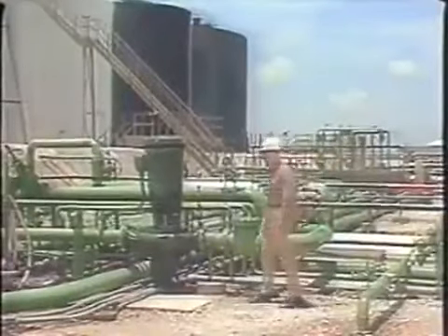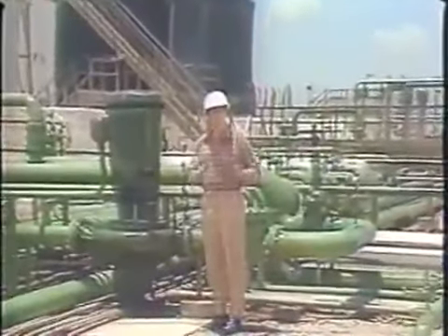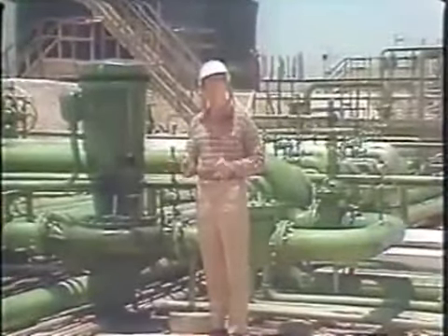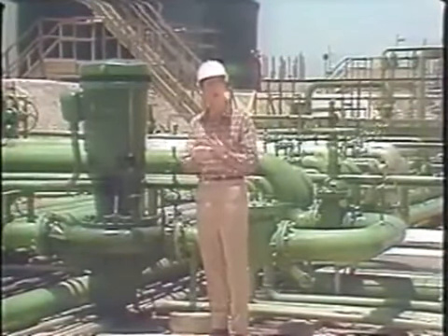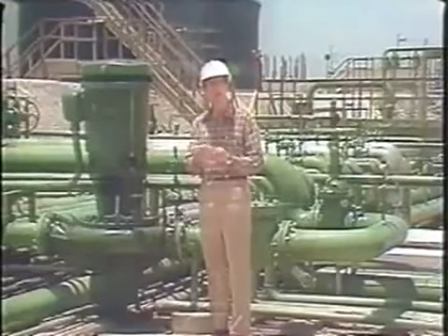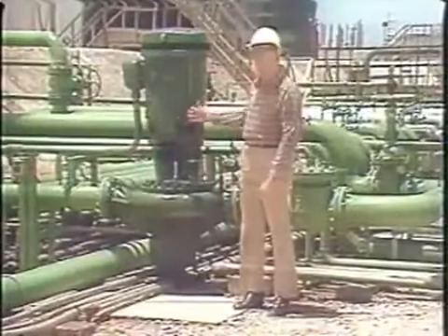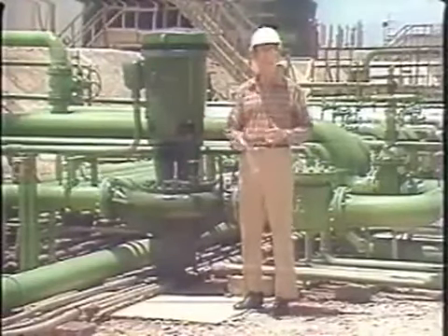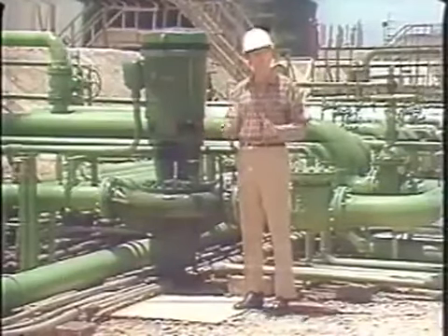Up to this point, we've defined a pump as a mechanical device that adds energy to a liquid in order to move it from one place to another. We've also pointed out that a pump has to be viewed as a portion of a system consisting of a supply, suction, pump and driver, and discharge. In this segment, we'll see why this approach is needed. In the pumping system, the driver is used to convert electrical or heat energy into mechanical energy. This mechanical energy is then converted by the pump into hydraulic energy to move the liquid. The liquid's hydraulic energy exists in two forms: velocity and pressure.